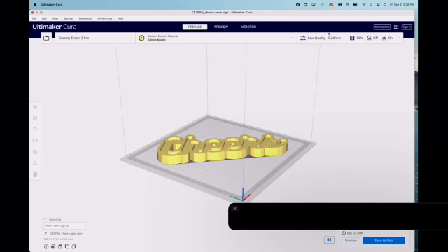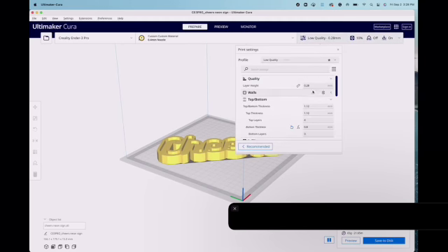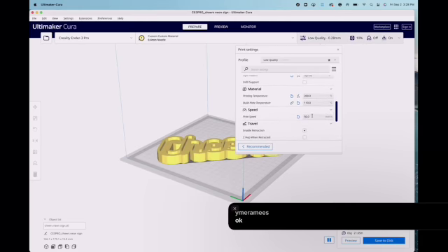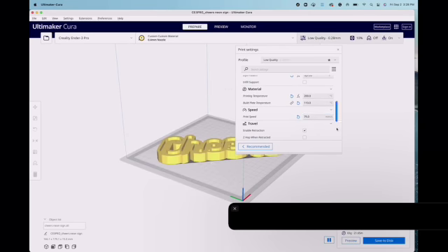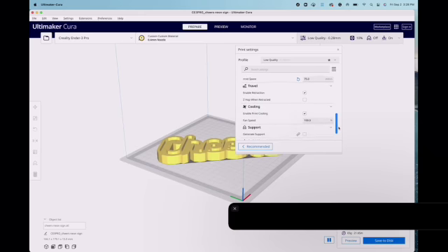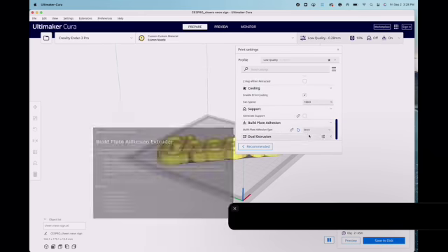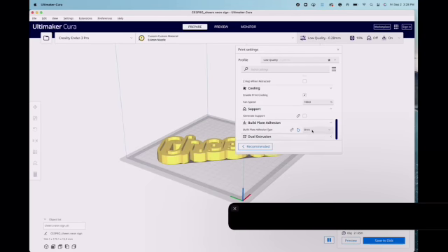But notice the grooves in there. You can play around with your printer settings. So I have this printing at a speed of 50. Let's say I update it and made it a speed of 75. You can put it up to a speed of 100. On your build plate, the build plate is how you print this out. So meaning, does it adhere?